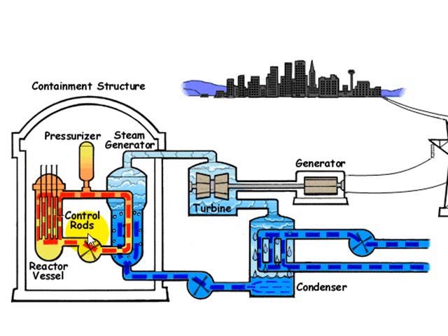The fission products continue to produce energy through radioactive decay, which just happens naturally, and this cannot be stopped. If the cooling system were to fail, the heat produced by this process would melt the core. This is a meltdown situation. The reactor is designed to contain the core even in this eventuality.